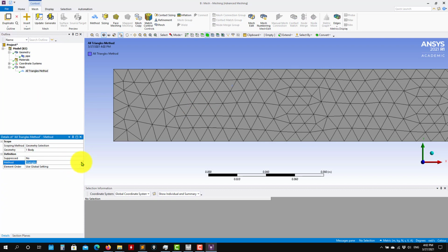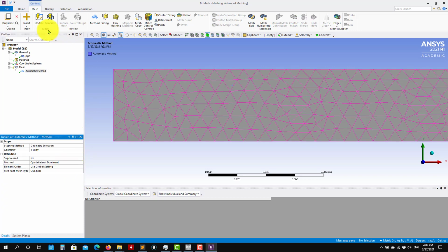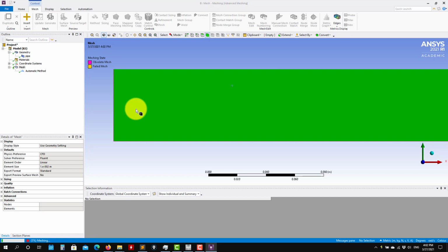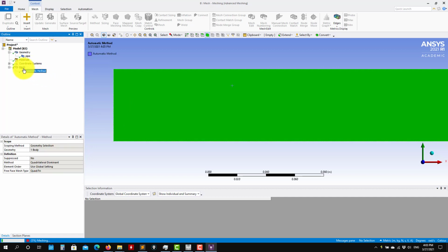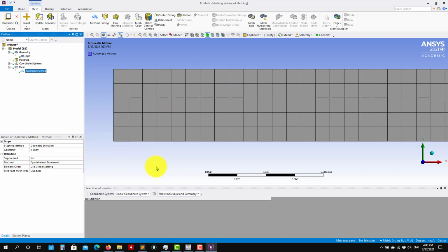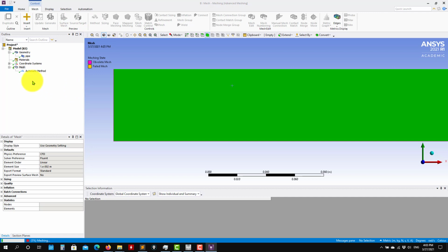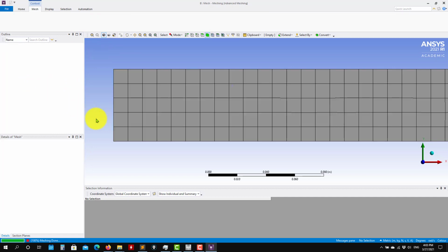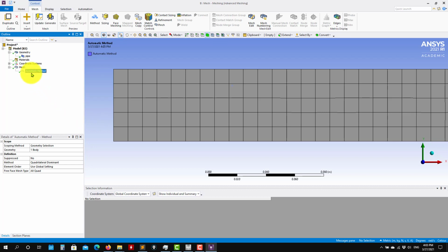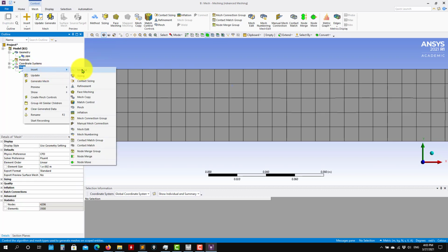Instead, when you have quads and they are perfectly aligned, these are a structured type mesh. Okay, so these are the best meshes, but they are not easy to generate. So let's work for the moment with this one. So see that you have here the options, quadrilateral dominant, and let's force everything to be quad. Generate. And we're done.